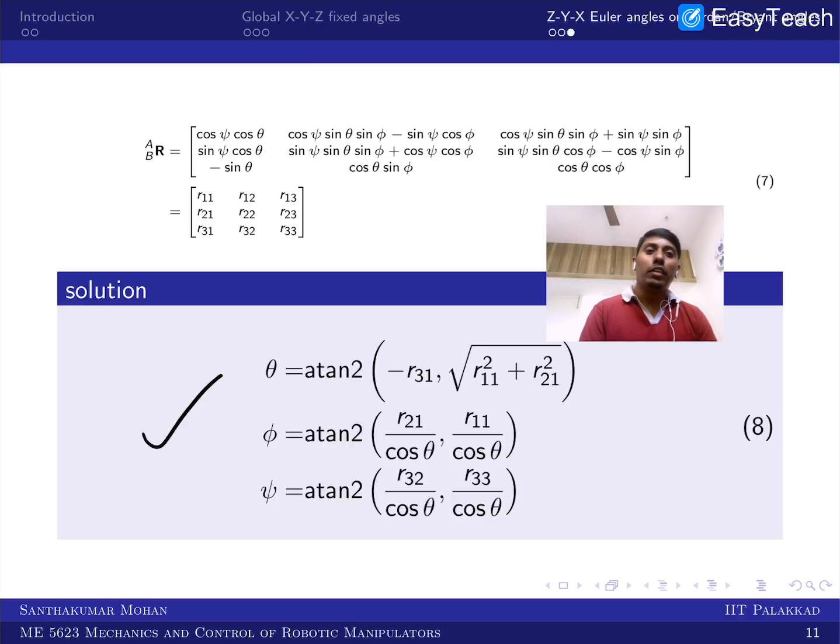The other one is based on screw algebra, which we call the screw transformation matrix or screw transformation. In this course, for serial manipulators, we are comfortable with the simple transformation method, the simple Denavit-Hartenberg method. Here we are going to bring in some parameters, which we call kinematic parameters, because we are going to describe the kinematic aspect. In general, the kinematic parameters are 6.